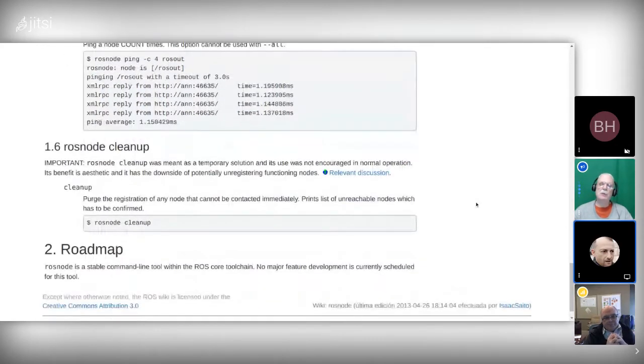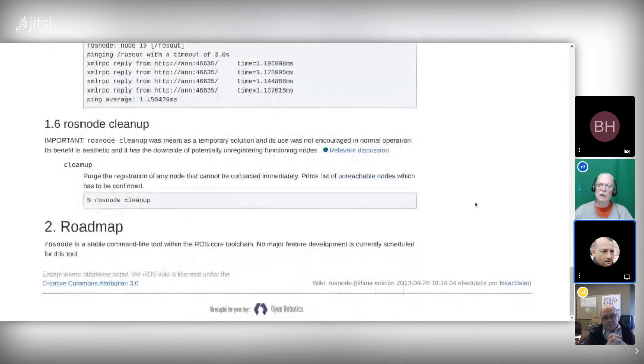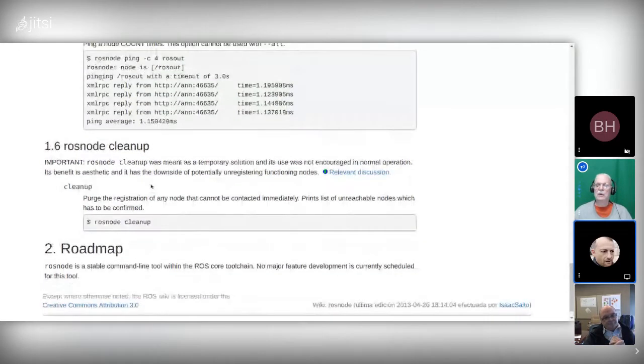If you push a button, it would cancel the current navigation. Whatever that's doing, I think you just want to do that same thing. So you could do it from a command line if you wanted to. Just put on the command line ROS topic publish whatever the command's called to cancel navigation. That would probably work, and you could do it at any point. Just type that in on a command line and execute it, and that should do it.